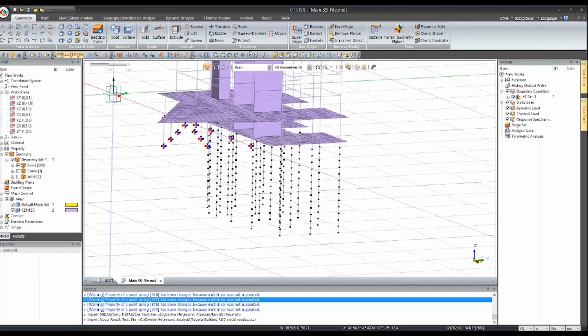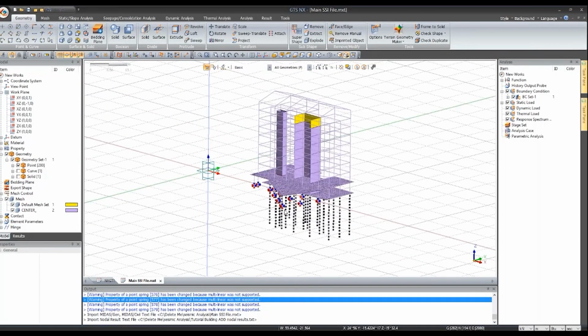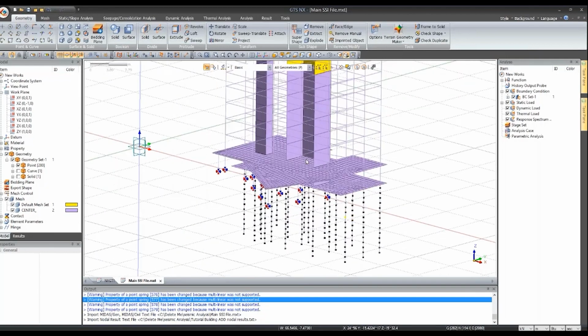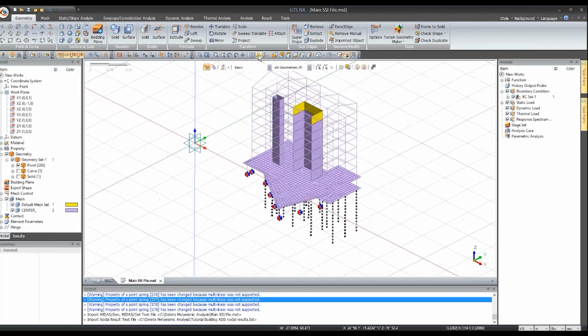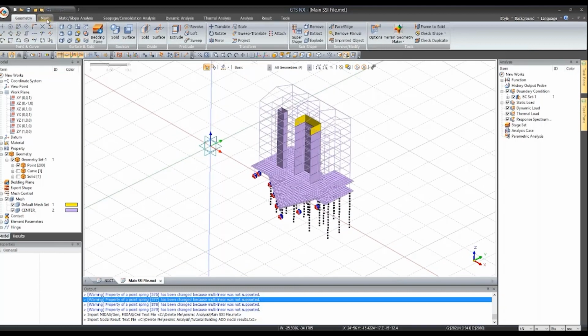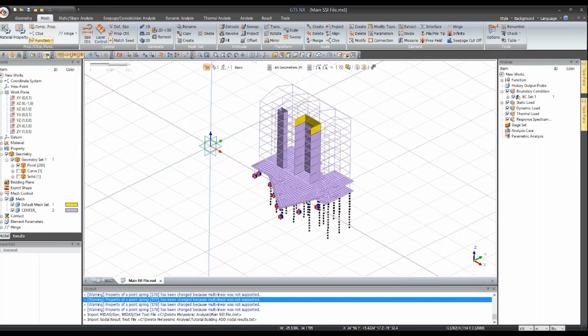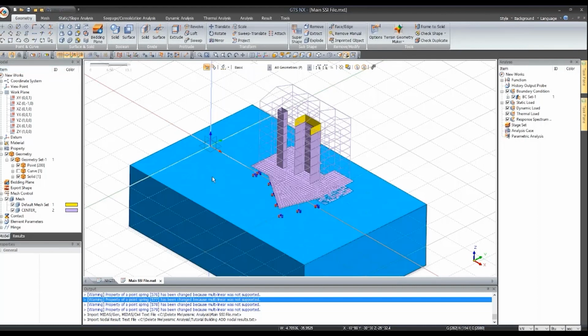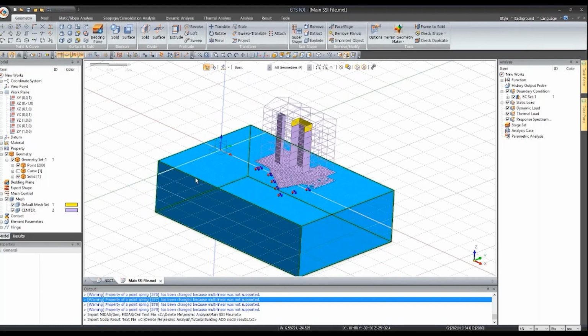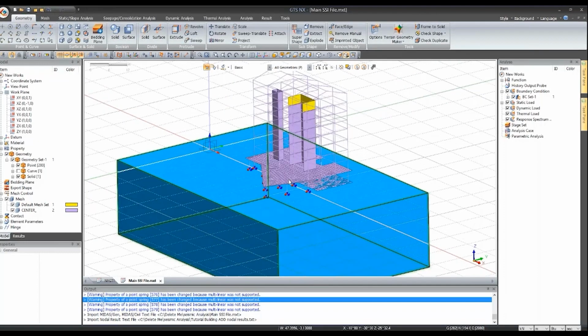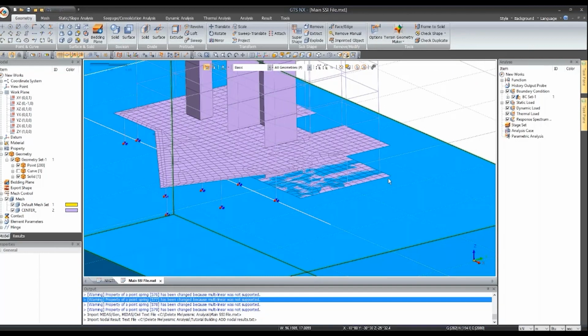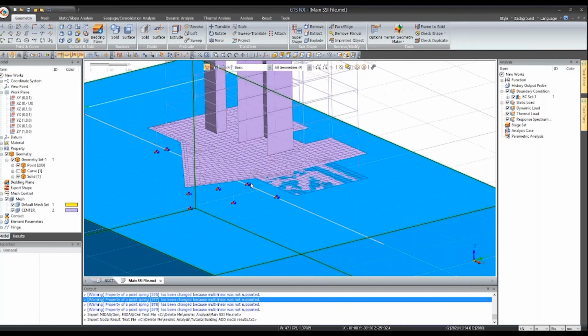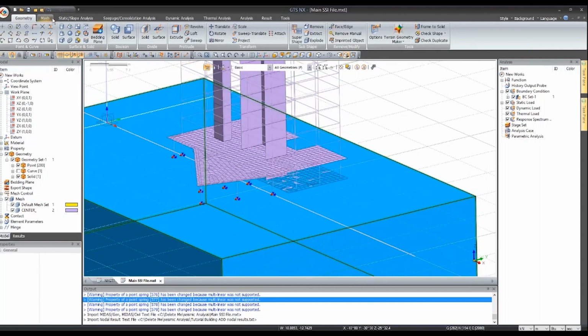So while meshing soil area, I will ask the software to consider these points. So that's the basic trick I'm doing. So here we have a solid with us. So our first step is to generate the geometry. So geometric modeling is done. And if you wanted to have a connectivity between raft and soil, then you need to convert the raft nodes into points as well. But as of now, it's not an important thing to do for this session. So let's go for material definition.